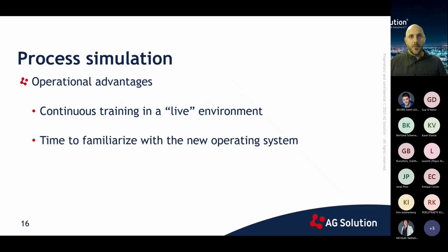The process simulation offers several operational advantages. It has proven to be a huge aid for the operator. He will have time to be trained and continue training himself in a live but digital environment. He will have time to familiarize himself with the new control philosophy and the new look and feel of the new operating system. All this will lead to a smoother startup.